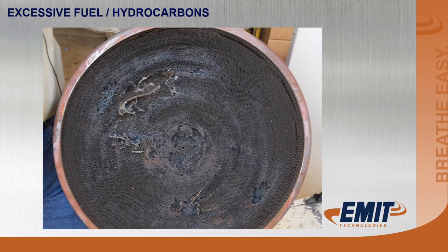And when they're running that unit, not only was the engine not loaded, so you had poor combustion performance and low cylinder pressures, therefore low cylinder temperatures, you were running on propane for a test run when the unit was set up for natural gas. So extremely high amounts of unburned hydrocarbons making it to the catalyst foil and actually combusting and burning on the catalyst foil itself. It's a pretty common thing to see. This is an extremely high BTU failure.